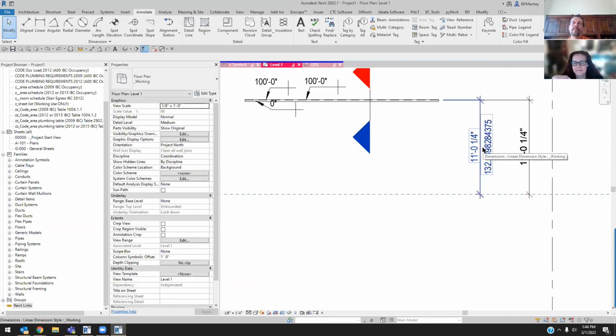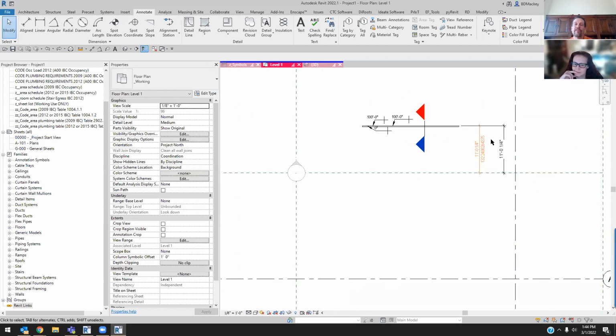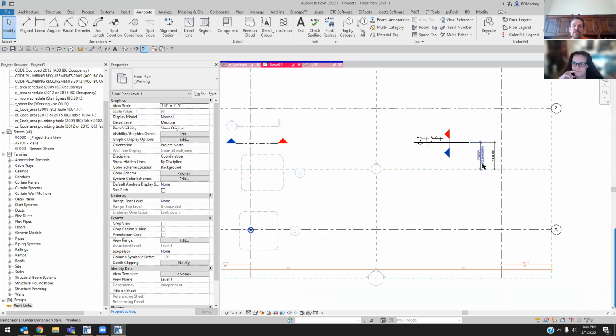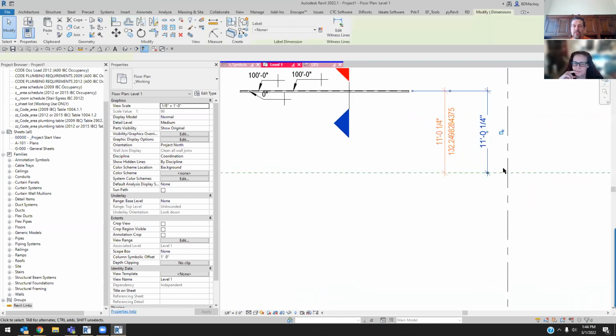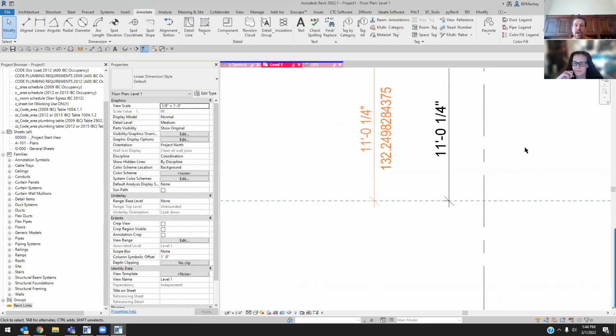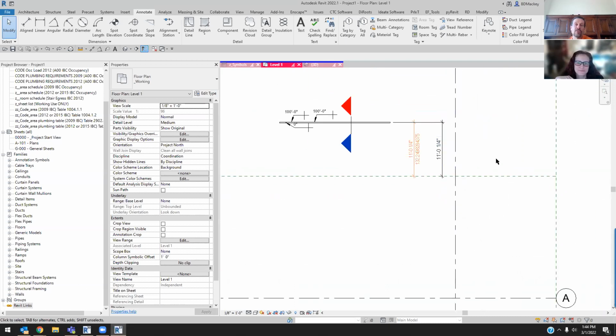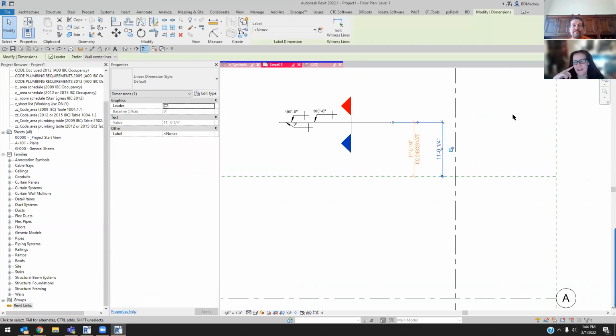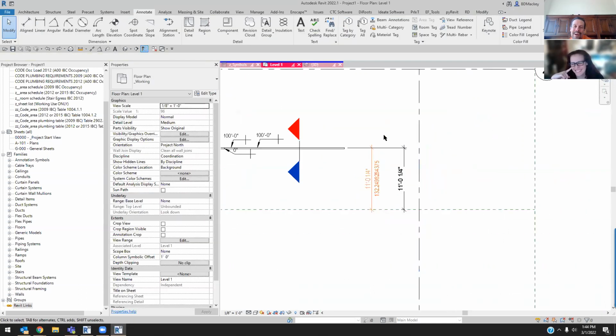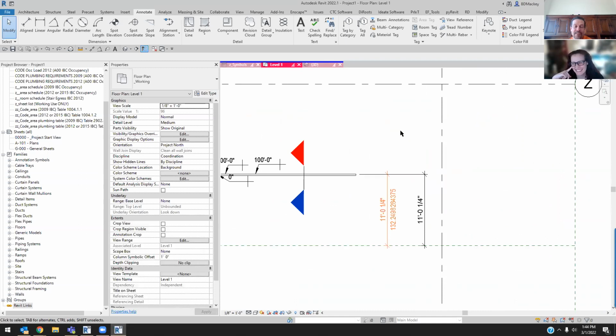Somebody screwed this up. And I've seen multiple projects where because people have it rounding to the nearest even 32nd of an inch, I get busts in dimensions. So for me, nope, actual dimensions go to 256. If you see that, your model sucks. End of story. I'm not gonna be nice about it. Your model sucks. You should have paid attention. And then yes, you should feel bad. Nope, I'm a consultant. I get paid to tell the honest truth.